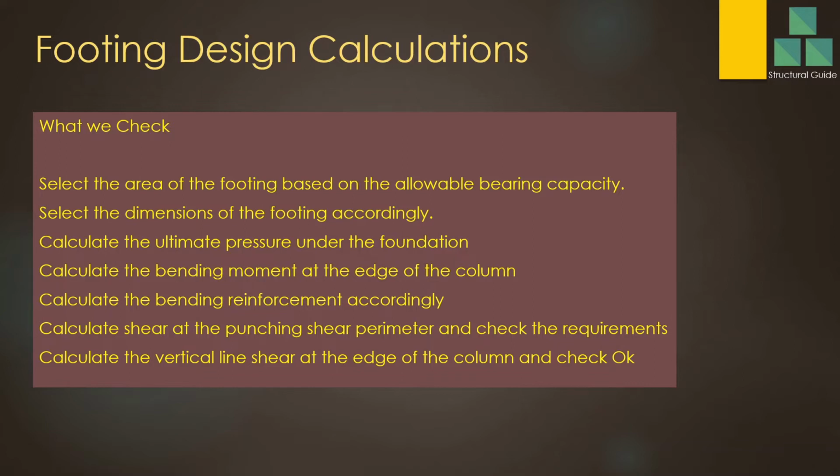But in thick foundations like raft foundations, we may use shear links as a measure. If the thickness increases, sometimes we may have to increase the wall thickness, or else we may have to have a column head like thing at the raft foundation. That also may be difficult to construct, so sometimes it may be easier to provide the shear links.